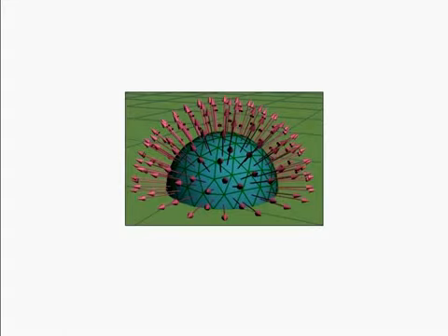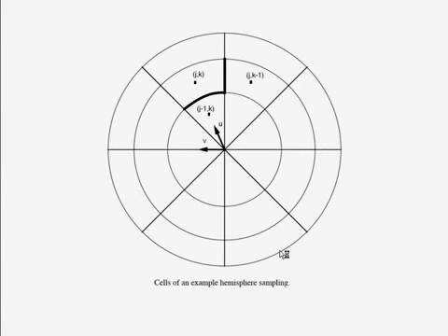And in simplistic terms, if you placed a virtual hemisphere above each sample as shown in this image and traced rays from each sample through each subdivision of the hemisphere, you can see that the more subdivisions, the more rays that are traced. Now this particular image is a very rough graphical representation of this process. A more actual account of the process can be seen in this image, which is from Greg Ward's paper called Irradiance Gradients.